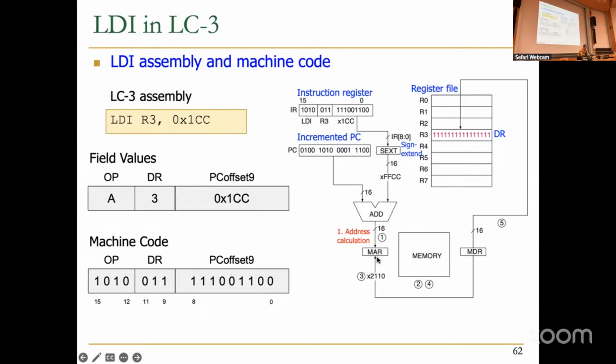That's the end of one state. And then you go to the second state, which is the memory access state. Memory accesses itself using the value in the MAR, the address in the MAR. And at some point, memory becomes ready and places the result into MDR.